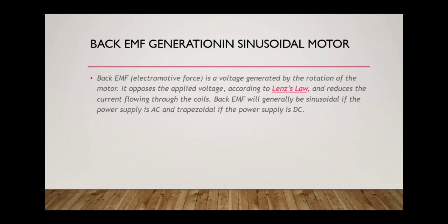Another thing we have to note in sinusoidal synchronous motor is back EMF generation. Now, first, let us know what is back EMF. Back EMF is a voltage generated by the rotation of the motor. It normally opposes the applied voltage according to Lenz's law, and the back EMF reduces the current flowing through the coils. Back EMF is generally sinusoidal if the power supply is AC and trapezoidal if the power supply is DC.